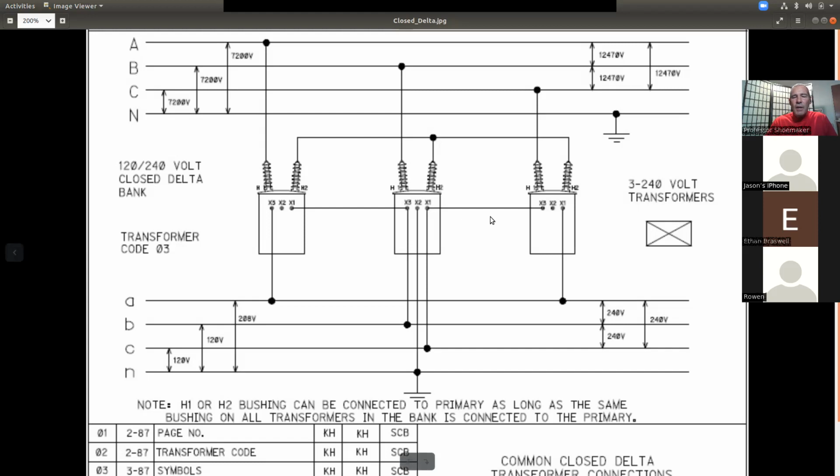So they've got tons and tons of three-phase motors in there running saws. They need more three-phase power. So closed delta is more apt for them to use in that kind of environment. They need the power of the lighting transformer and a lot of three-phase power. So they're going to add the third transformer in there to suit their needs.